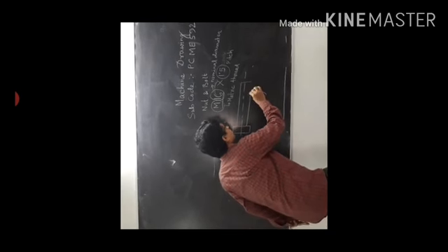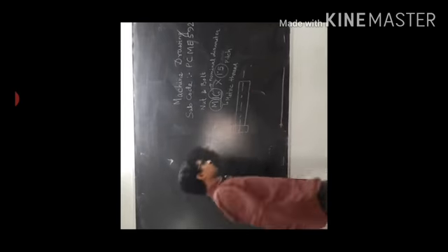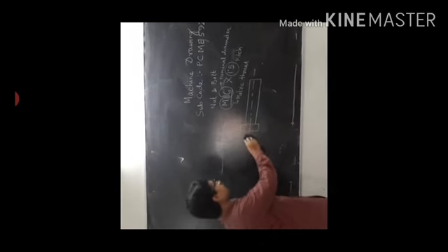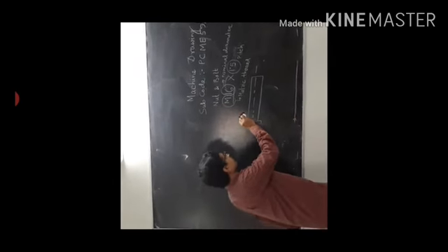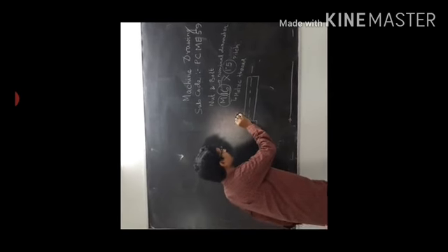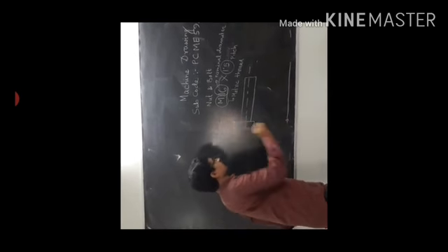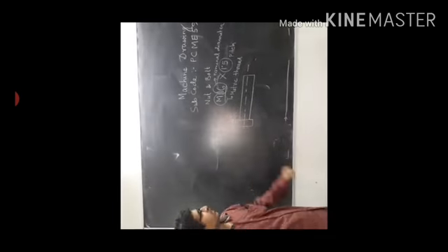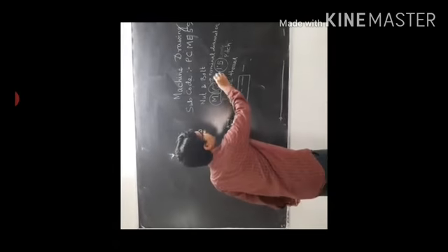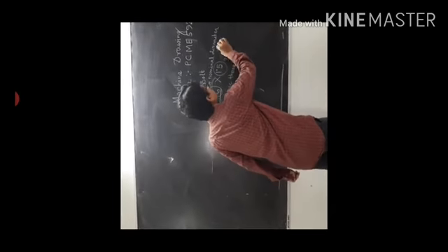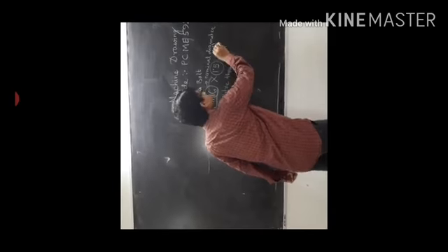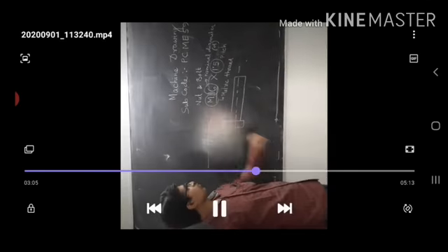This is the total distance. This is the width, the thickness of the bolt head. 16 is the nominal diameter represented by small d, and all your relationships are given with the help of empirical formulas in terms of d.